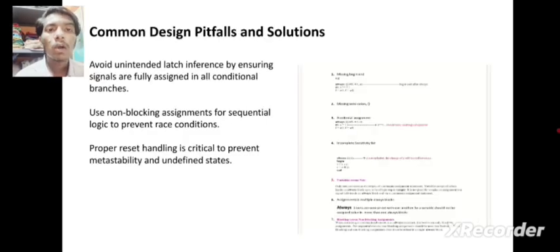So the next one is the common design pitfalls and solutions. Avoid unintended latch inference by ensuring that signals are fully assigned in all conditional branches.